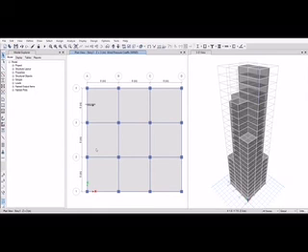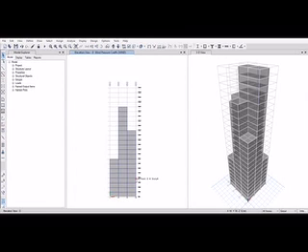First go to elevation view and select section D and click on OK. Select all the shell with all story option. The corresponding wind pressure coefficient for this side is minus 0.25. Go to the assign shell load wind pressure coefficient option. Enter the value minus 0.25 and direction and leeward and side click on apply.